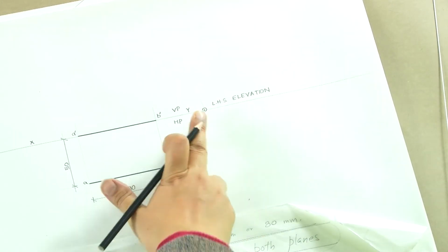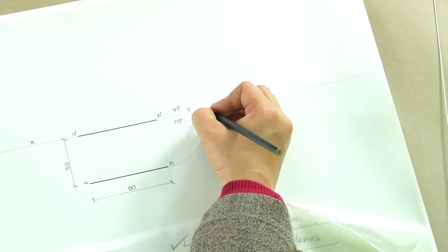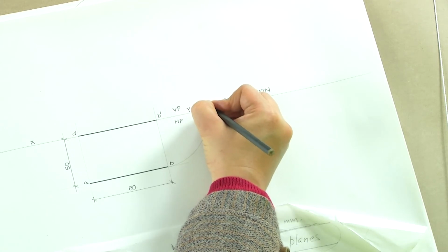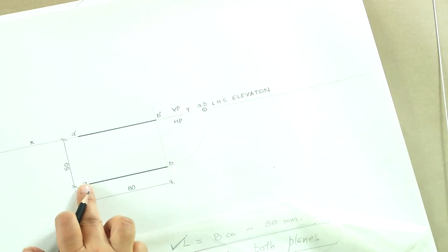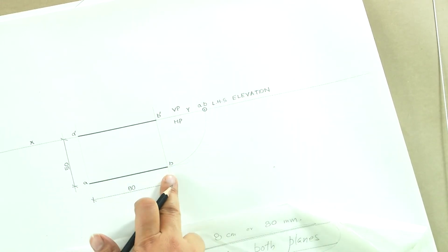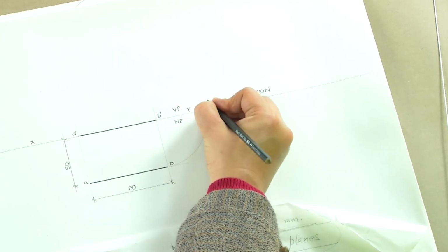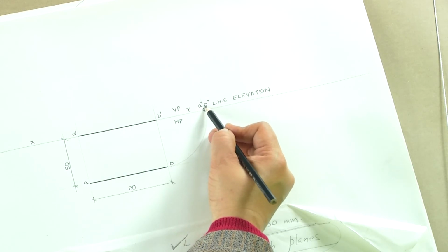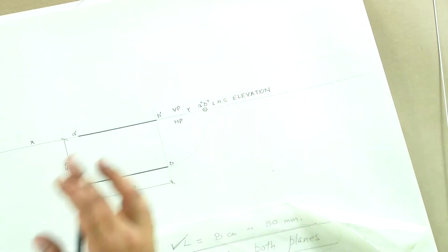And what is this point? This point is actually AB. So, we are actually seeing this A, B. Now, if we write AB, AB is the nomenclature that we use for the plan. So, we will either write A double dash, B double dash, which means that A is in the front and B is at the back. You could also put a bracket here, either of the two.